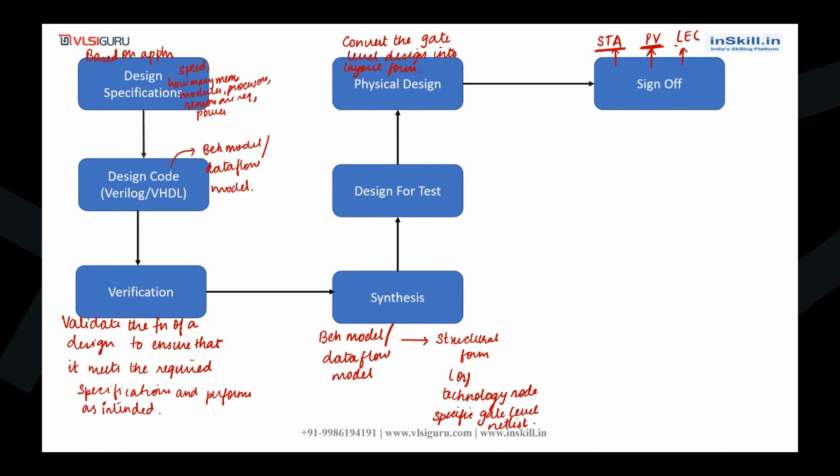And next is LEC. LEC stands for logical equivalence check. It is actually done in order to check whether the final design is logically equivalent to the original design or not. So that is what LEC is.